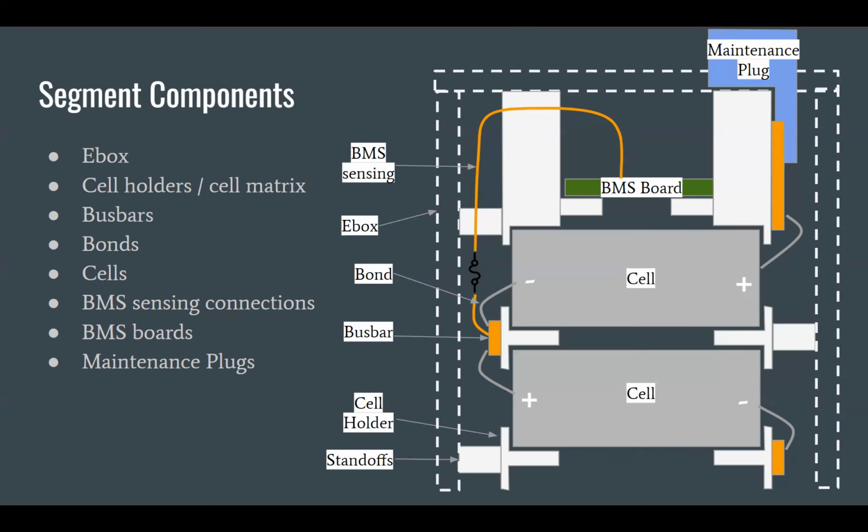It became so challenging. And not only that, the maintenance plugs were such terrible quality that they would break when you used them as intended. It was so bad that now, in retrospect, we would be able to move forward for next year's designs with a much shorter maintenance plug and a much shorter set of connectors in the BMS ports, and the whole battery could be an inch or two shorter, which would be way better.